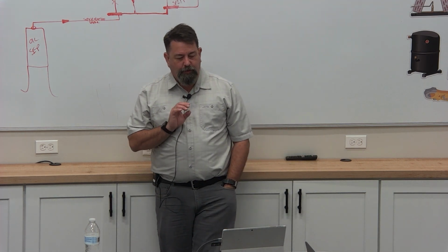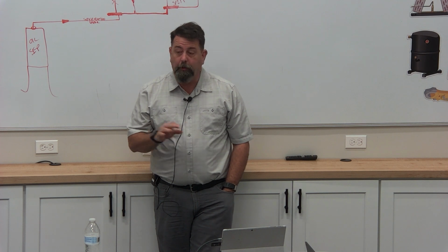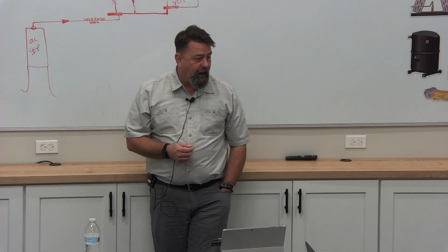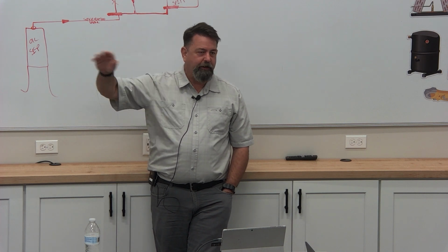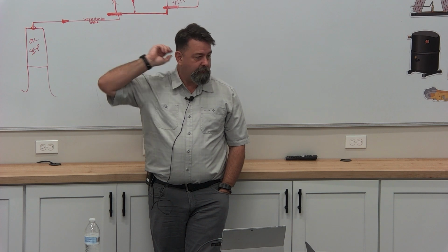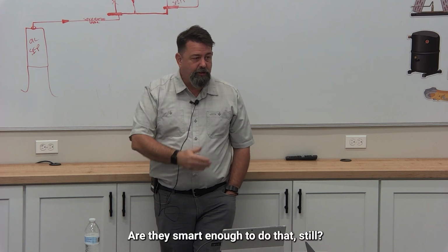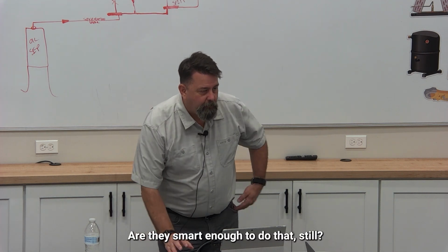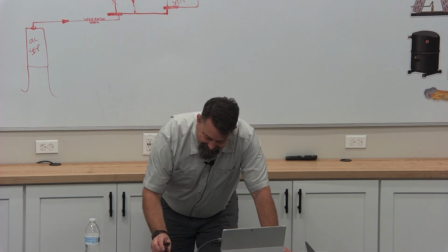So when I go to replace this motor, and I go to the parts store, I'm going to tell the guy, this is clockwise, looking at it from the back. Clockwise lead end. And he's got a whole list of every motor manufacturer that he sells and which way they look at it, because it does vary, there is no standard. Are they smart enough to do that still? Yes. Well, the computer system is.